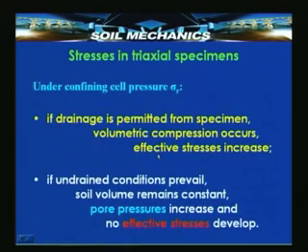Further, the stress sigma r that is applied all around is nothing but a confining pressure that confines the sample, and the reason why we apply this is it helps us to simulate the confining pressure that exists at the depth from which the sample has been taken out.